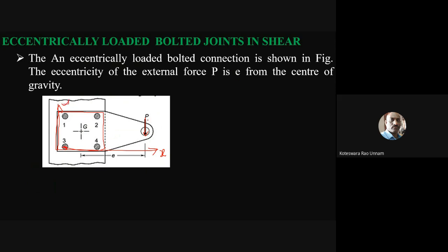So here your load is acting along the y direction. That means your plane of the bolts is the xy plane and the load is in the y direction, so both are in the same plane. So I can call this the load which is acting in the plane of bolts.